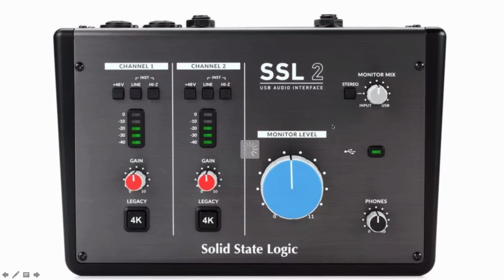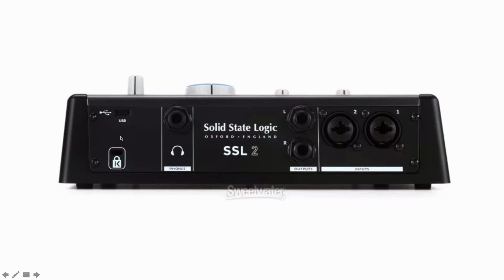Let's go back to the back of this device. So the back has the USB slot here. Usually after you buy an audio interface, it always comes with a cable. You can use that cable to connect the audio interface to your workstation. And here's the headphone jack. Also be aware that the size of this jack is actually 6.5 millimeters, and some of the headphones you have for your cell phone are 3.5 millimeters. So always make sure you either get a converter or get a headphone with the 6.5 jack. And then the output here, the L and R, is for the monitor, and this is the mic input.